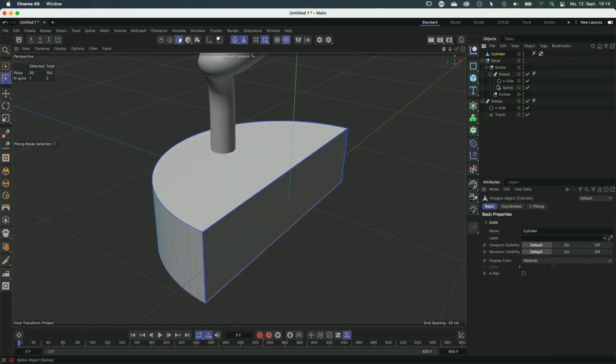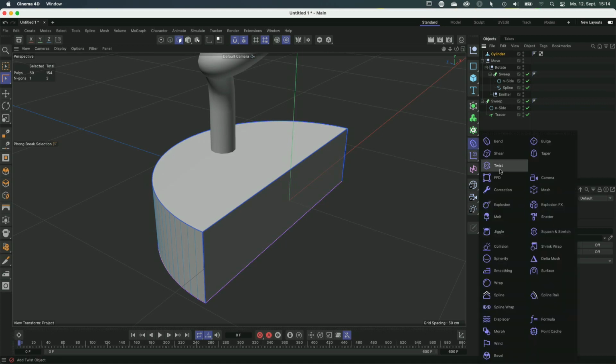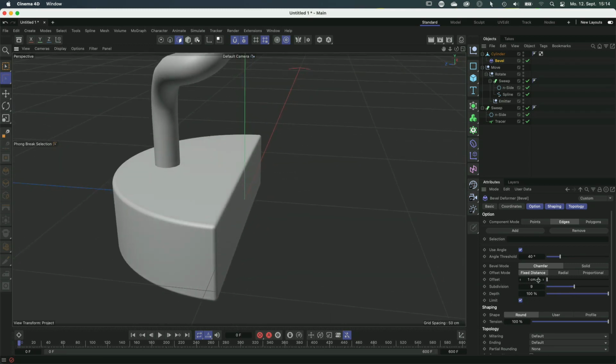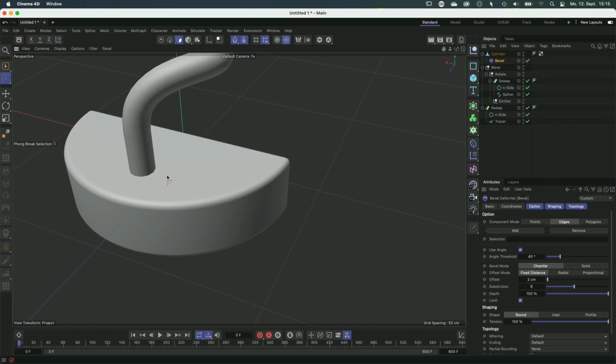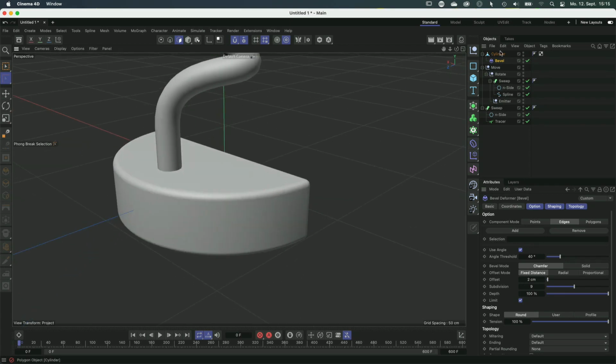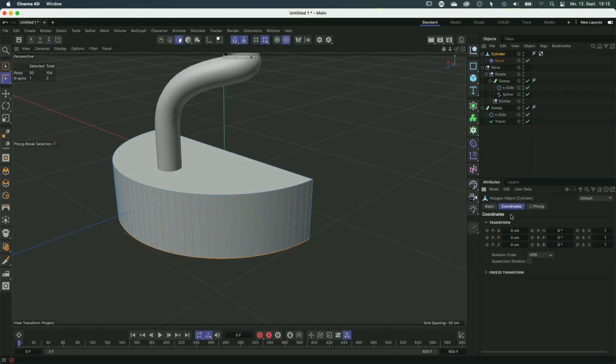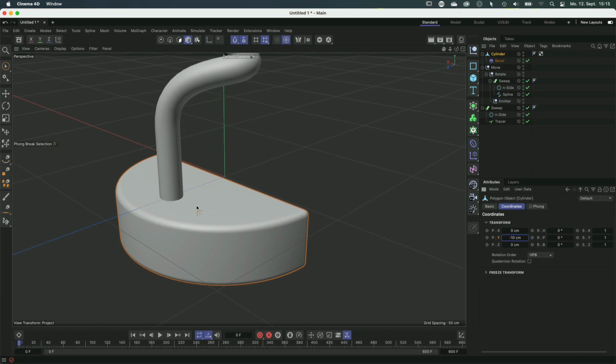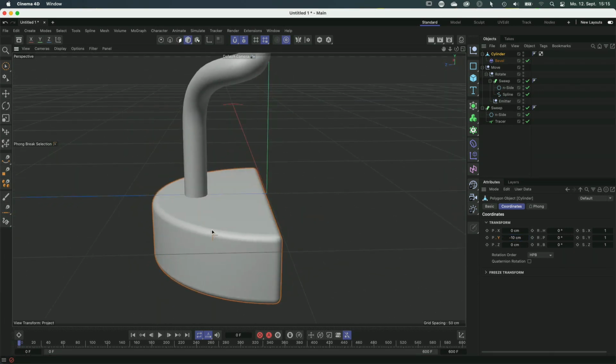All right? And then the next thing I want to do is, well, let me actually think about what I'm going to do next. I'm going to create a bevel deformer. So let me go in here and hold down the Shift key. This way the bevel deformer will automatically be created as a child. And I'm also going to bring up the subdivisions here. So here we go. That's this part, and it's still procedural, so we can adjust the offset a little bit as we want, also later. Then we need this part where the wire is coming out from, but before I do that, I have to bring down the cylinder by 10 centimeters or so. That's good. Yeah, 10 centimeters is correct, because the height here is 20.